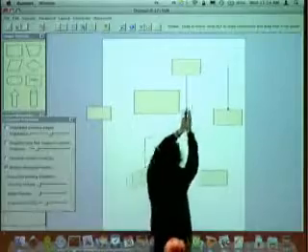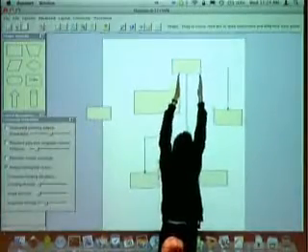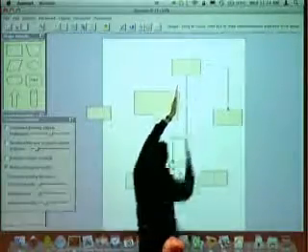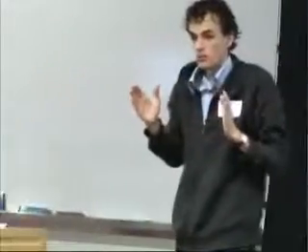So in this case, because our channel of free space is here, we would nudge just in the line of visibility and up to the edge of the shape there, and the nudging would just space them out equally along that shape from their center. So effectively you get a nice spaced layout in that case for free, without doing any extra work.